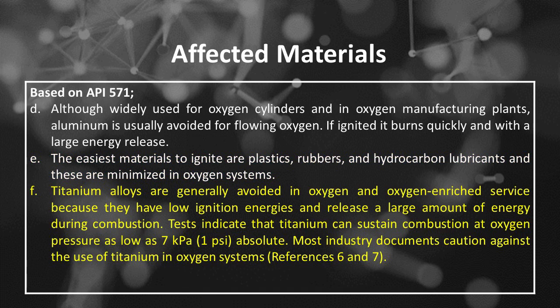Number F, titanium alloys are generally avoided in oxygen-enriched service because they have low ignition energies and release a large amount of energy during combustion. Tests indicate that titanium can sustain combustion at oxygen pressure as low as 7 kPa, 1 psi, absolute. Most industry documents caution against the use of titanium in oxygen systems, references 6 and 7.